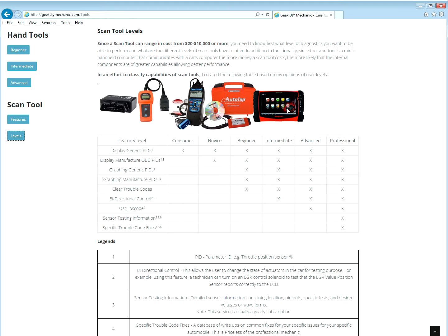If they don't, maybe there's a wiring issue. If they match, maybe it's a sensor issue. So that's why you'd want to combine it. It reduces the overall pieces of equipment you need, and especially since it's a Snap-on, it's going to have built-in test descriptions and expected results.